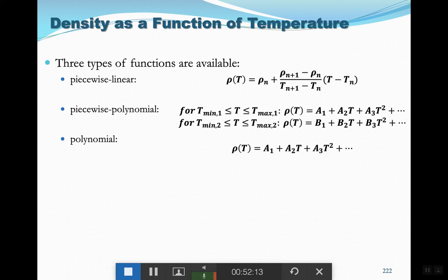Now you could go with the Boussinesq model. That would be one way of doing it, of course the easiest way. But even if for any reason you wanted or you had to consider density as a function of temperature, you could use this model.